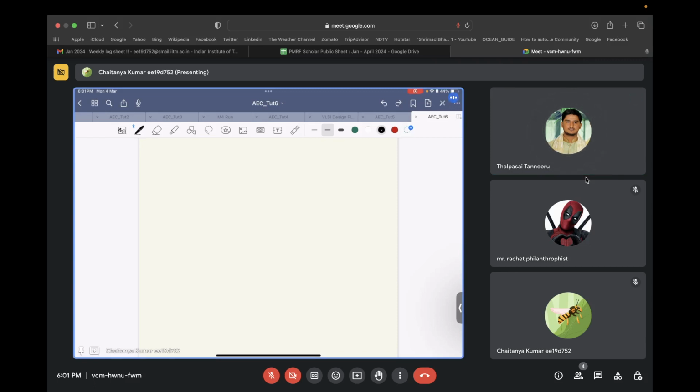Let me think of something. So we can start with a basic structure of a common drain amplifier. What we can do is, let's say we have an input source Vi, which is connected through a capacitor to the gate of the transistor. The drain is fixed to VDD, and then we have this thing. Let us have it this way. So this is being biased, let's say, using a 10 microamp current source with a current mirror.